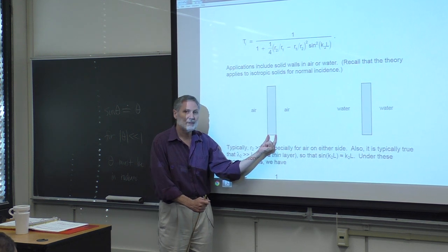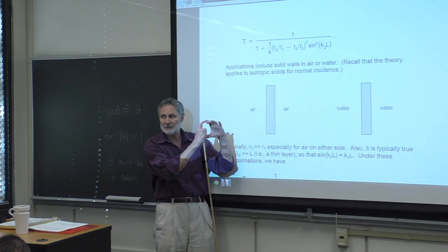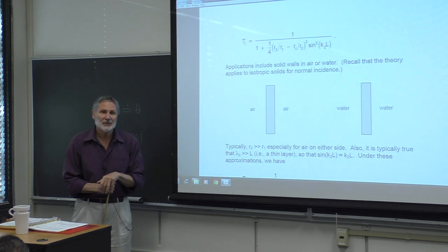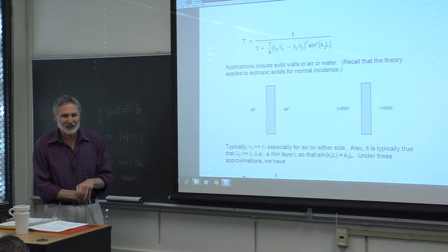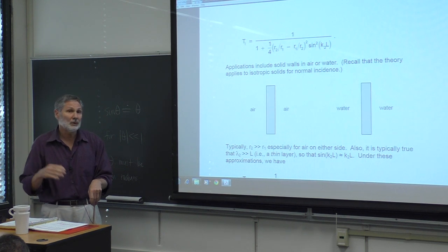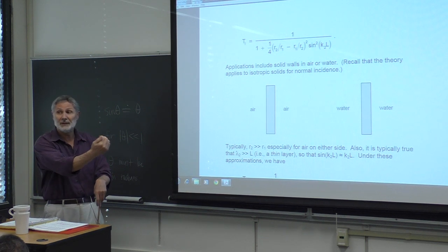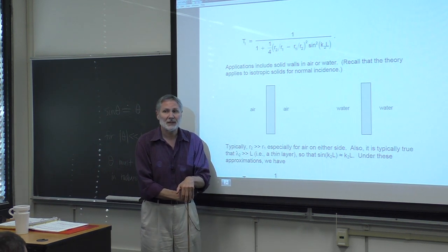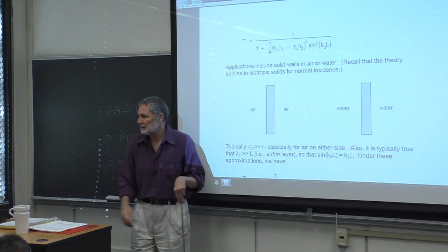When you multiply it by this, you get the mass per unit area. You take the mass per unit volume, multiply by the area, you get the areal density. So it's a pretty obvious fact that if you want to insulate sound, if you either want to prevent sound from getting out or prevent it from coming in, you want to use material that has a high mass per unit area, a high areal density.